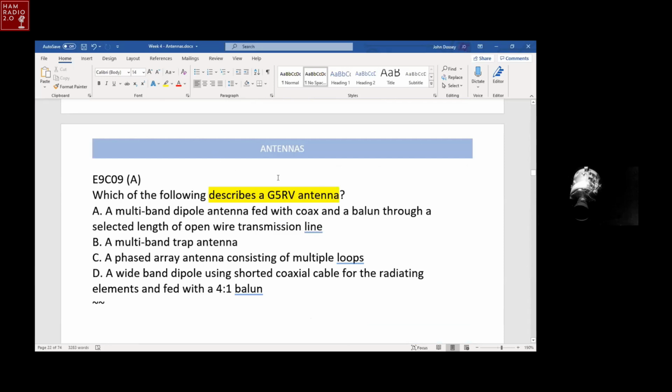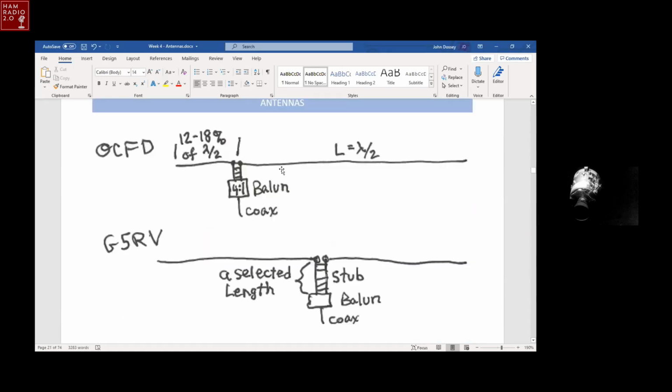Well, that's funny you mentioned that, because that was a question that was asked on one of the nets yesterday that Gordo replied to, of how to run something on a small lot. It was more for the ground radials, and you can run a zigzag pattern for them. But as long as you don't cross the radials, like say if you have a 40, you don't cross it across the 20. They're separate, but a zigzag pattern can fill a small lot. And the same thing with the antenna itself. But you lose radiation pattern off the way the primary pattern comes off the radio. Yep, just get a wire up and get it tuned and off you go.